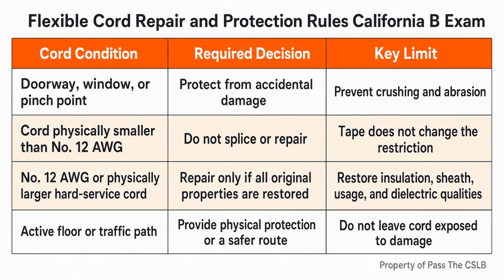Temporary power often begins at a pole or portable generator, and both have details that are easy to oversimplify. A temporary wood power pole must be at least 6 by 6 inches when square, or 5 inches in diameter when round. It must be at least 20 feet long and embedded 4 feet into the ground. Those dimensions are not a substitute for evaluating the actual installation, soil, loading, bracing, utility requirements, or electrical work. They are the minimum temporary pole dimensions identified in the source material.